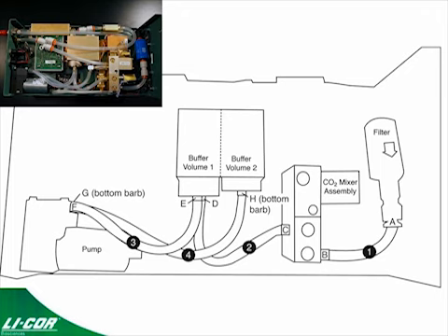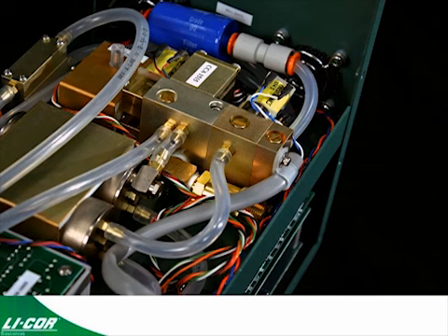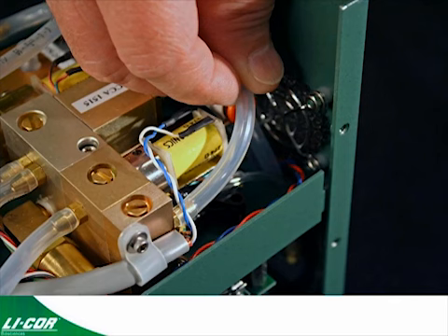Although I demonstrate removing the tubing from the buffer volume disconnected in the carriage, you will want to be sure not to remove any of the components from your instrument. Remove the tubing from the installed components. Tube 1 is removed by pressing in on the orange or red fitting on the quick connect, which will release the tube from the quick connect fitting.